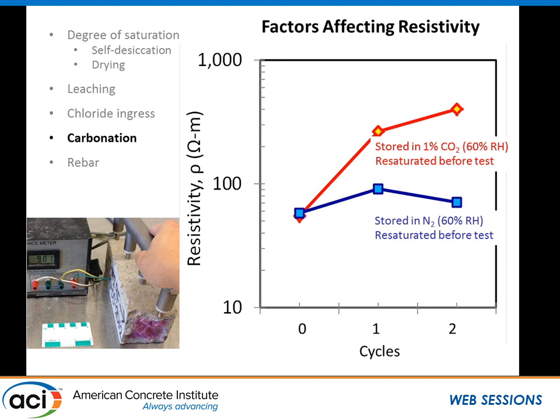When the concrete carbonates, the pore solution composition changes dramatically. An uncarbonated concrete is dominated by sodium, potassium, and hydroxyl ions. Typically, its pH is somewhere in the region of 13.5. When you carbonate concrete, the pH of its pore solution drops to around 8. And the pore solution composition is totally different. And it will look great from an electrical resistance measurement because the pore solution is non-conductive, or virtually. So carbonation will definitely give you this apparent increase in the electrical resistivity, which is not real.